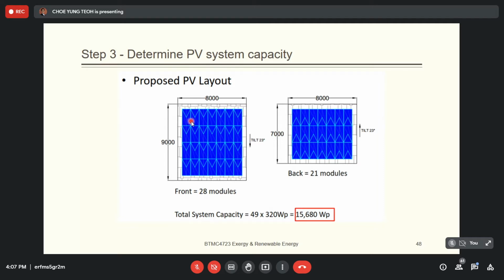Bypass can be automated or by time calculation. As long as the resistance is too high, then you just bypass. Of course, you don't need to put a bypass on all the pieces, because some of the pieces definitely will not have any shadow. So don't waste your money doing the bypass for every piece. Just do it on the specific pieces.